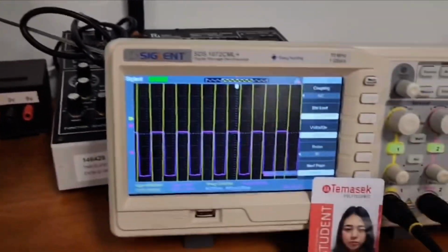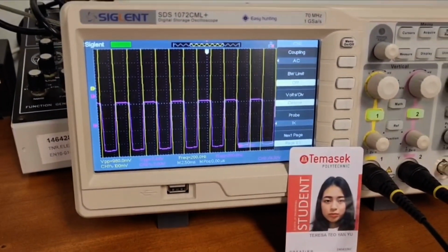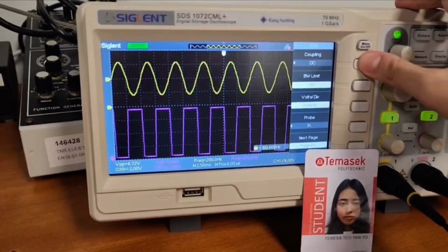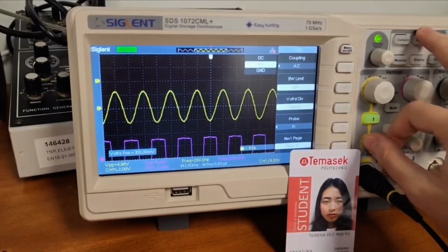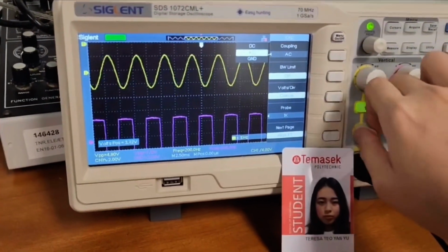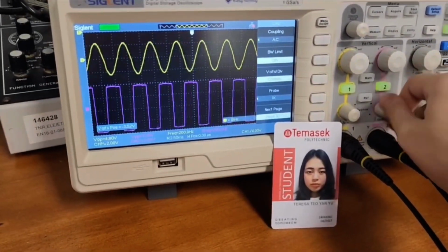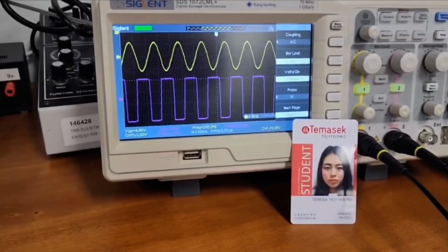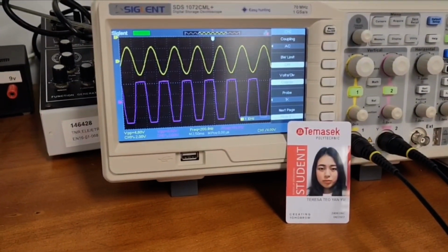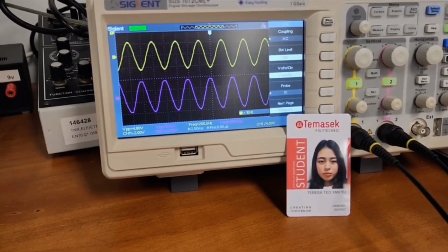To adjust your waveform for better viewing and comparison, always press auto once, adjust the waveform to be AC and adjust the width and height. Appropriate lengths should occupy 2 or 3 boxes. At 200 Hz, the voltage input versus output just shows a 180 degrees inversion from 4.8 volts to 6.32 volts. If I turn the trimmer anymore, it will be saturated and clipped.